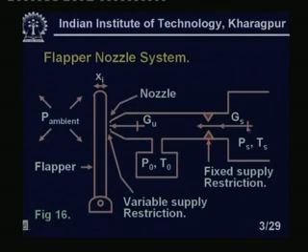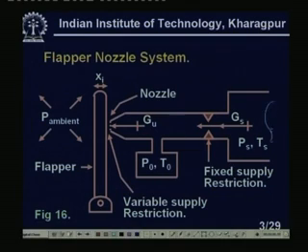So the constant pressure source is this one, GS and PST. This is our constant pressure source, right here you see. This part is connected to a nozzle. One part is the nozzle, which is free, and continuous air is leaking through this one. This is a continuous supply, and this is measuring the pressure, which corresponds to the position of the flapper, right?